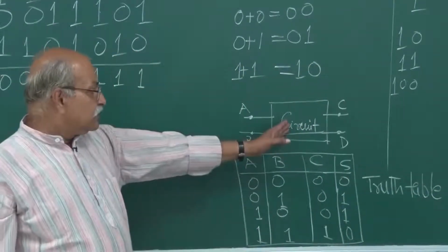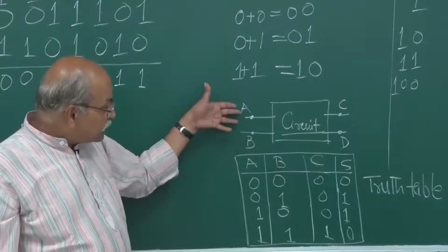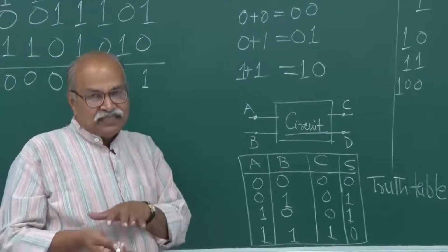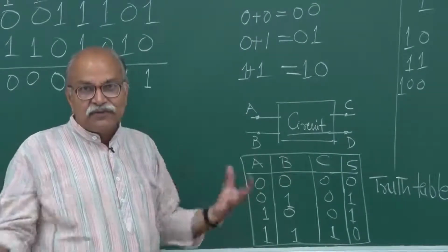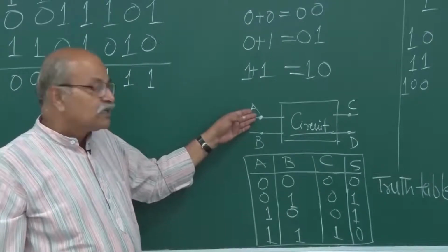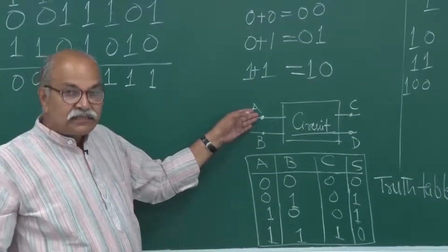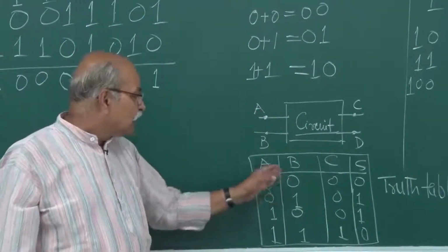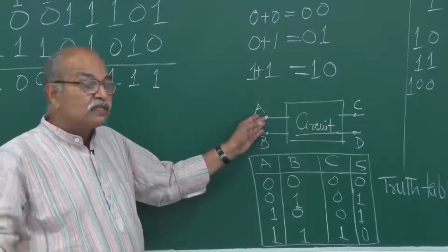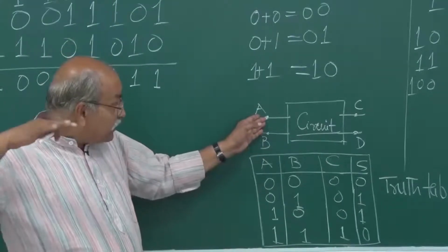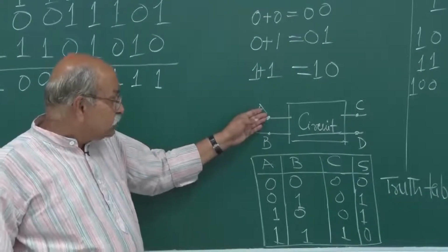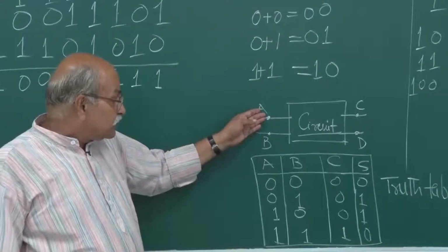And our circuit will take these inputs, that means voltages we will provide, low and high. We have to predefine, normally say 0 to 0.8 volt or 0 to 1 volt is low. So if I apply 0 volt here, 0.5 volt here, that is low, and that will be treated as 0. And anything which is predefined more than 2 volts, that I can define, if it is high, more than 2 volt, then that is 1, and similarly for B.